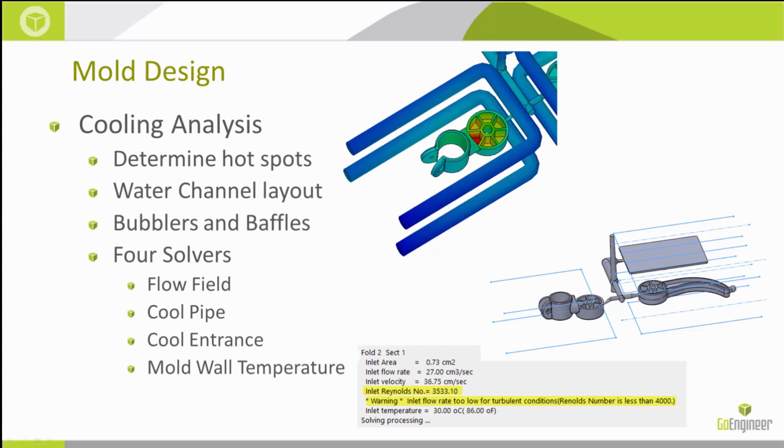As we know, cooling occurs throughout your entire molding process, from the fill stage through ejection. So your rate of cooling will have a significant effect on your part dimensions and is a factor in part defects. Our key is to cool the part uniformly. It'll reduce residual stress. It also minimizes the risk of warpage and cracking.